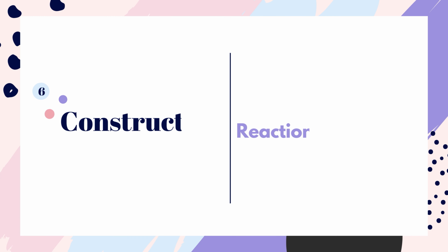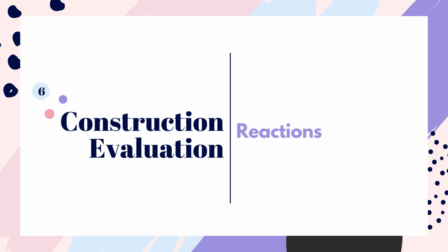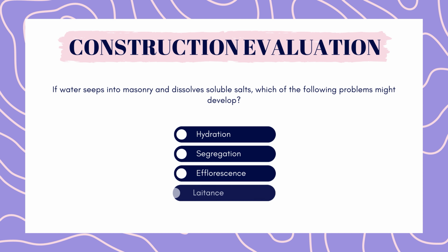Next up is construction evaluation. If water seeps into masonry and dissolves soluble salts, which of the following problems might develop? Hydration, segregation, efflorescence, or latence? Pause here to answer.